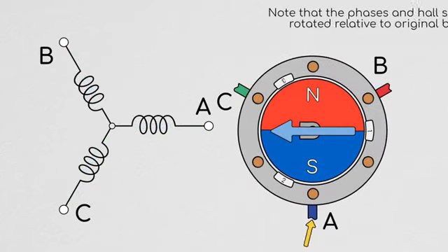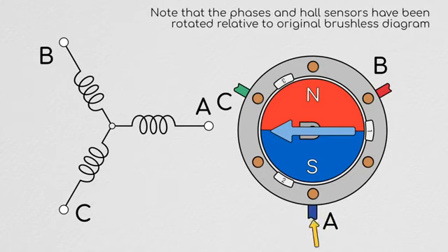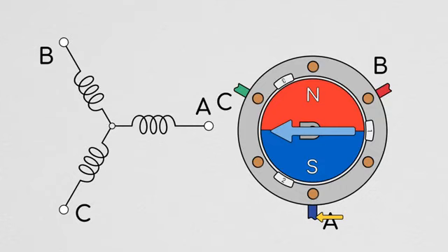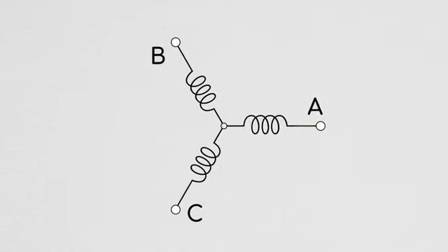Because at the end of the day, it doesn't really matter which direction the current is physically running, just the direction of the magnetic field induced by that current flow. However, in terms of measurement and control, it's easier to think about current running through phases than magnetic field generated. Now, with this new notation, a current into phase A will correspond to both a current vector and a magnetic field vector strictly to the left. A current into B will produce vectors 60 degrees south of east, and C will be 60 degrees north of east.